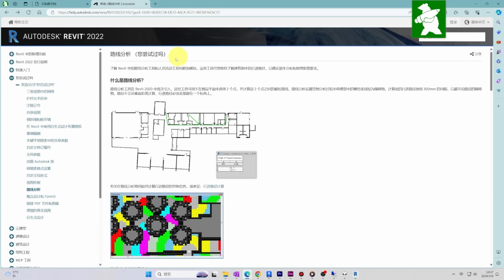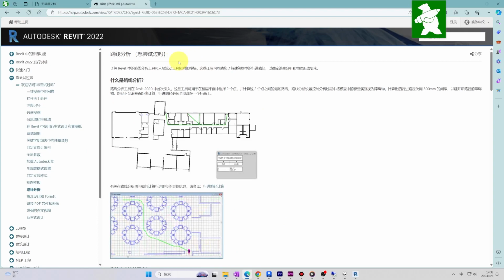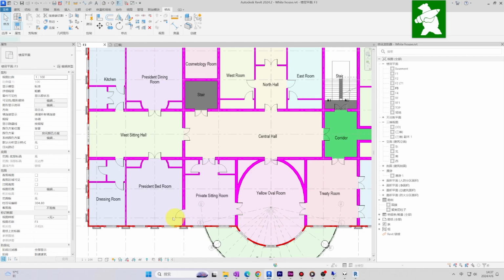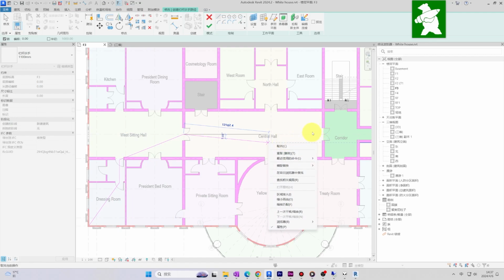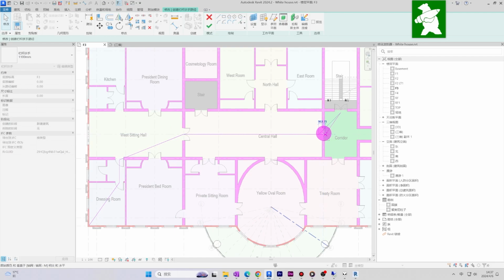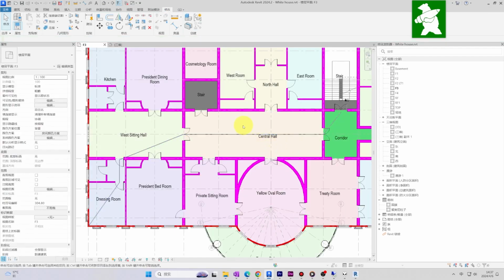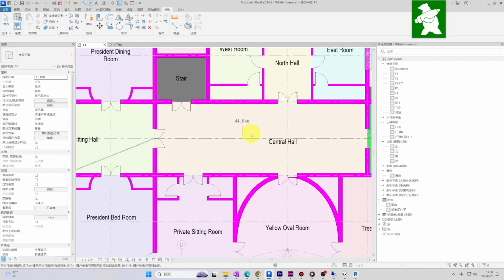The evac path function was introduced in Revit 2022. Before that, the method for creating the evacuation path was drawn manually, and because Revit does not have polylines, a very common element used in AutoCAD, in order to be able to draw the evacuation path and calculate its length, a previous method was to use railings instead, which may seem stupid, but it is a way to do that.